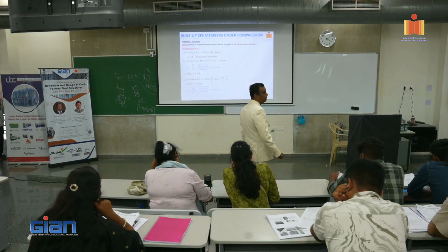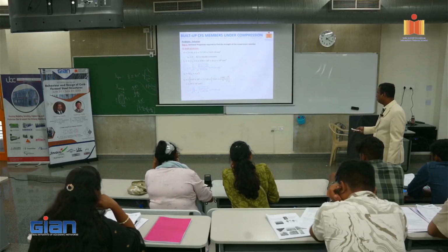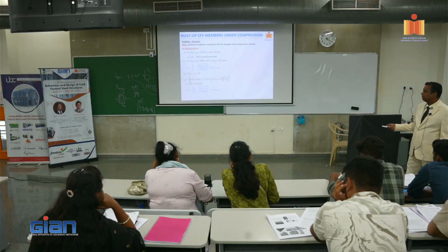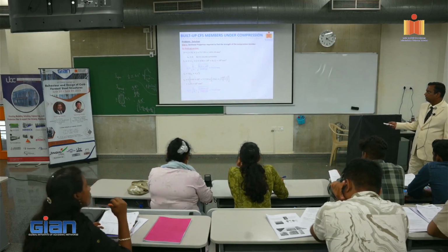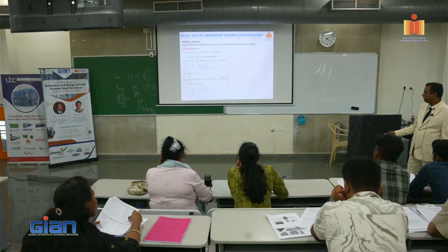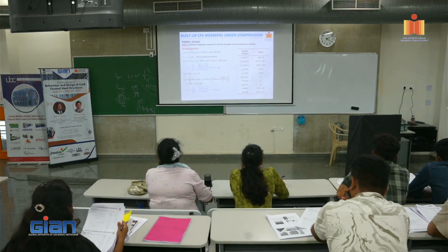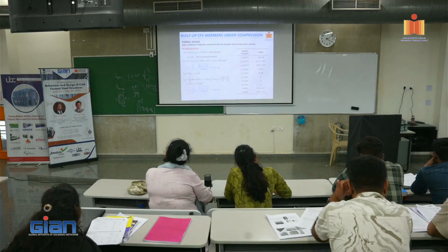Now Ry equal to root of Iy by A, right? Now when you do so, you get 33.28 as the value for Ry, and that is for this cross section here. So you have to calculate Iy and then you calculate Ry, and this is the section property for the combined section, not the individual section, combined section, right? Any questions so far?